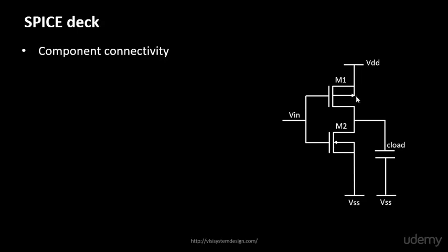There are significances of these arrows. I'll come to that in a bit. So this is how your PMOS looks. This is the substrate terminal of your PMOS and this is the substrate terminal of your NMOS, and this is the NMOS symbol. The reason we are doing this is because in your spice deck or in your spice netlist we need to define the connectivity of your substrate as well. Substrate is a potential pin on your NMOS and the PMOS, the transistors. So you need to define the connectivity of that substrate pin as well. Okay, and we also looked into the significance of the substrate pin, where it tunes the threshold voltage of your PMOS and NMOS. So we have already looked into all those.